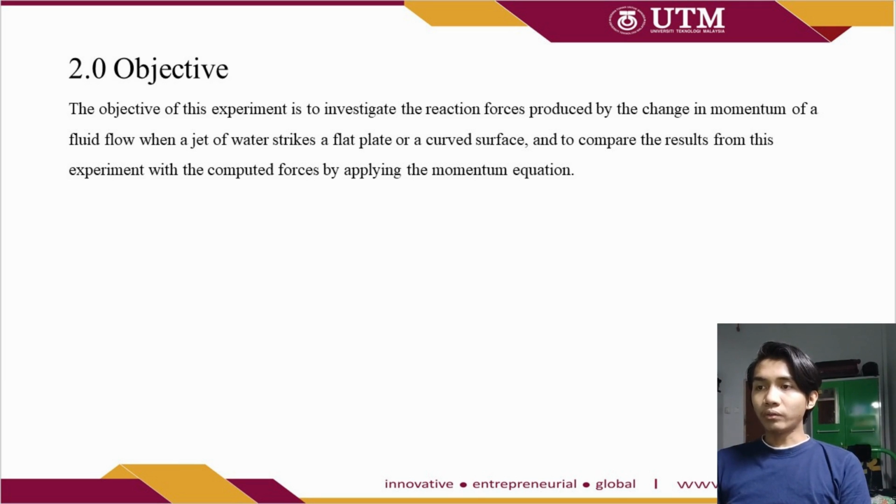Next is objective. The objective of the experiment is to investigate the directional forces produced by the change in momentum of a fluid flow when a jet of water strikes a flat plate or curved surface, and to compare the results from this experiment with computed forces by applying the momentum equation.